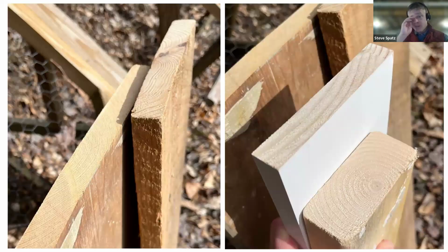And this isn't just about breaking the wood down and turning it into other commodity goods. We're talking about sheet goods and engineered structural timbers and things like that, but also just the actual physical characteristics of what our lumber looks like that we work with now. Trees that are old growth, tightly grown together in a forest canopy, are slower growing. And so the growth rings that occur annually in that cycle create a denser, more dimensionally stable piece of lumber when you cut that tree down and turn it into dimensional pieces for structural purposes. That higher density structure is more stable over time and will not be as affected by moisture loading to the dimension of the material.